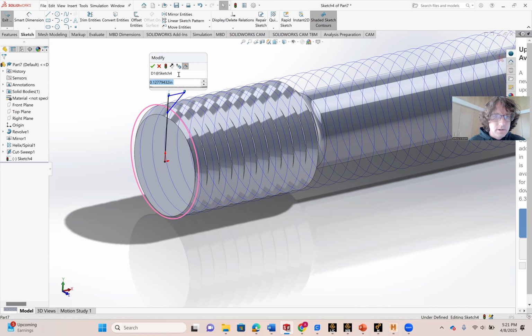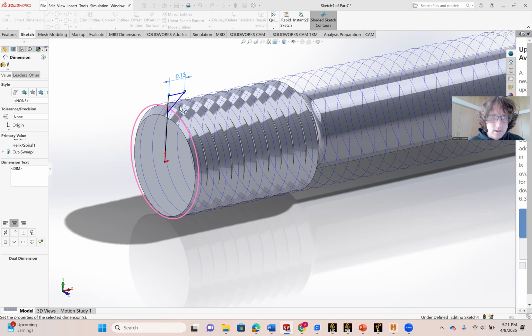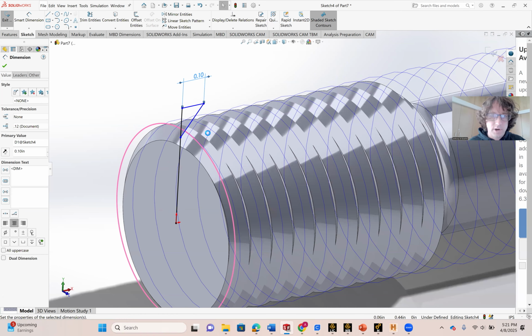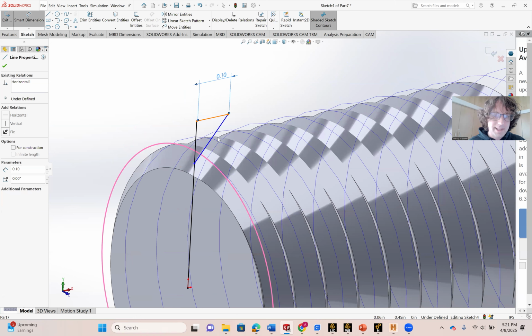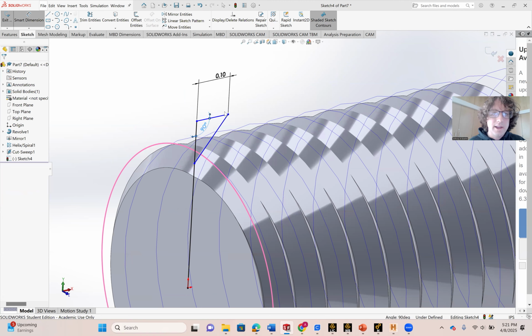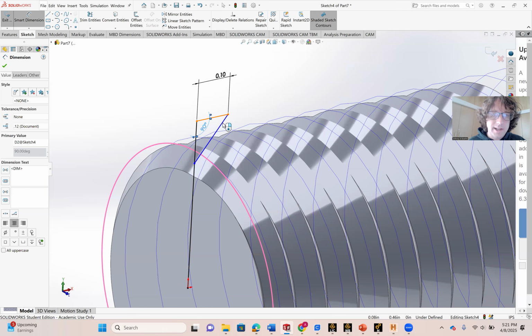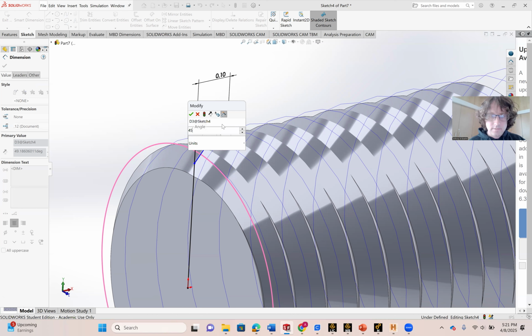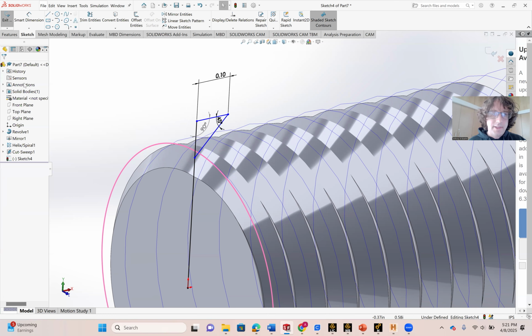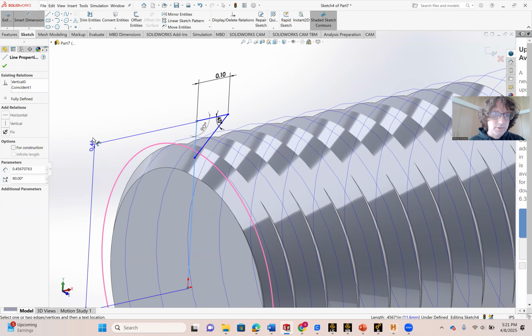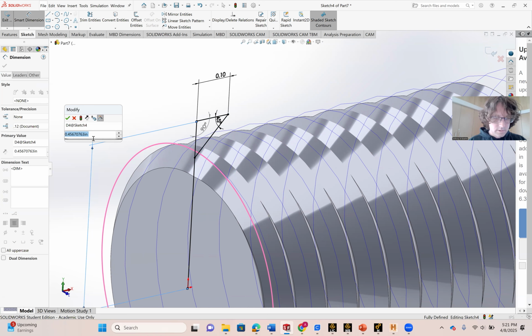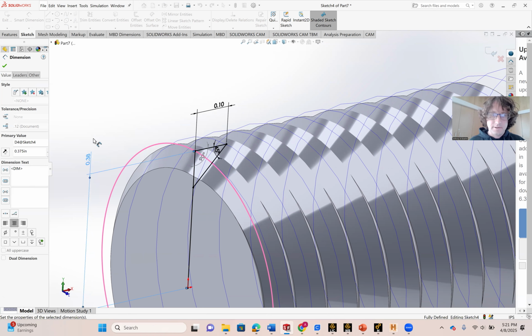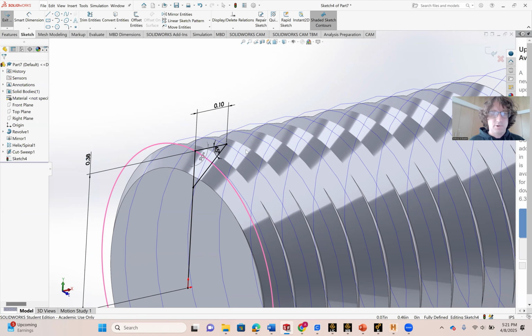So let's do point one. Much faster. And then we're gonna just make, yeah, let's smart dimension this guy and that guy. We'll make that 90 degrees. Okay. And then we'll also make this guy to that guy 45. Okay, looking good. And then we will also make this guy 0.375 because that's half of 3/4, and this is a 3/4 10 bolt.